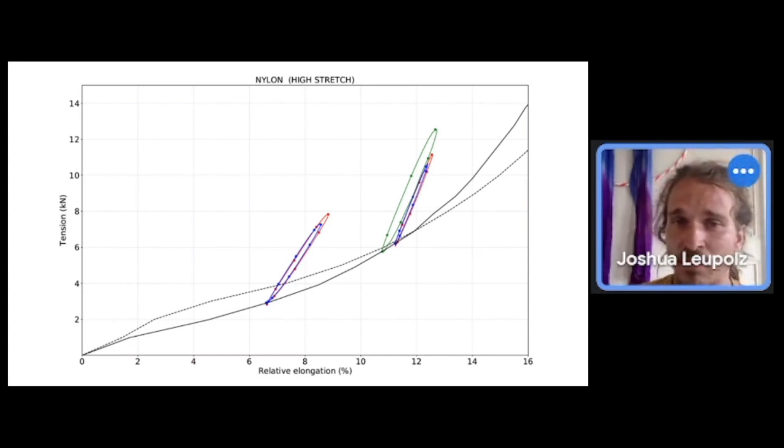And this also shows really beautifully how we cannot really rely on the values which the manufacturers give us at the moment, because with this blue and red line, if you get these values, we know how the webbing is behaving doing leash fall and doing bouncing. And these values we can compare to other webbings. The black line is just something which is after all the dampening happening, all the viscoelastic effects going on. And this is really hard to compare and actually get the conclusion how the webbing will behave during bouncing. So my proposal is we need this curve here, especially the steepness of the line, to know and understand how much our webbing is stretching.